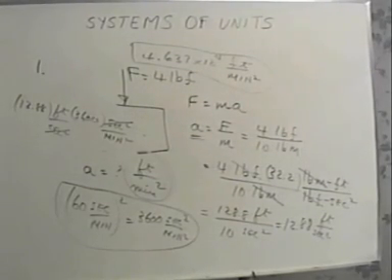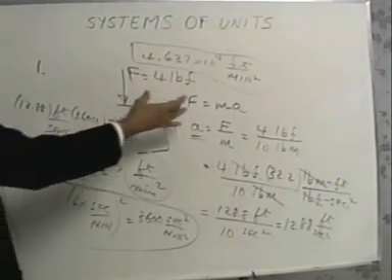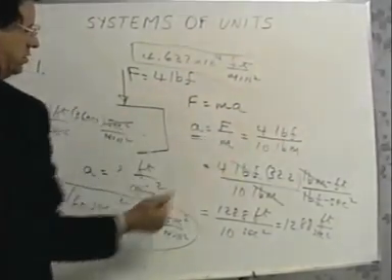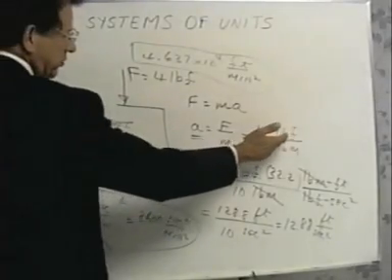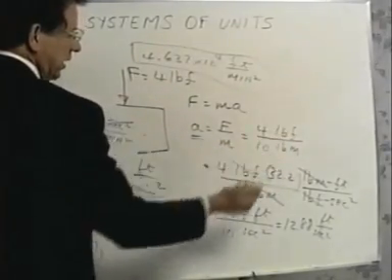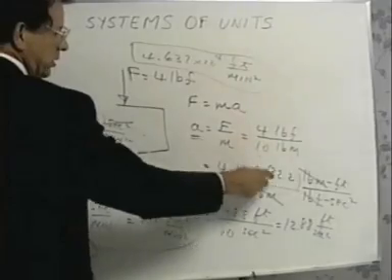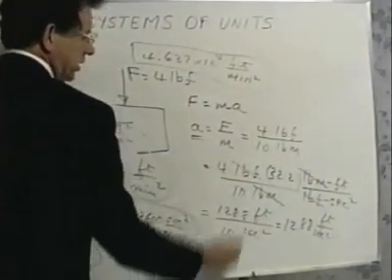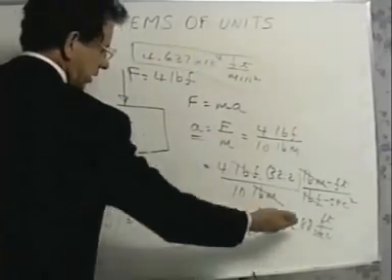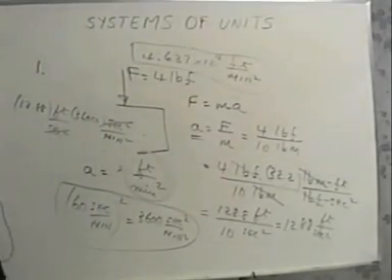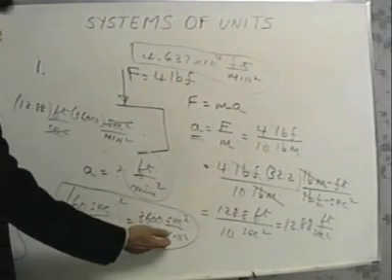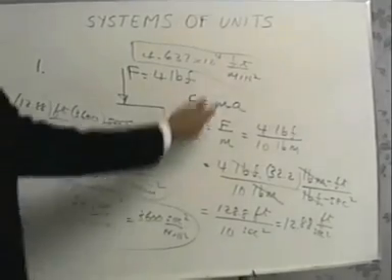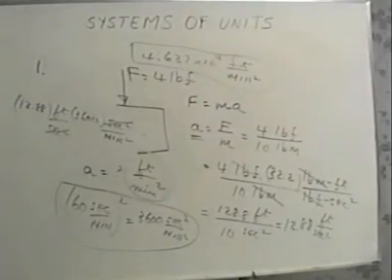So there's the answer. Notice how we approach the problem. We start off by using the basic Newton's law. We watch the units to see how to make things compatible. We know that we need to convert LBF into LBM so we can get a cancellation by multiplying by 32.2 pound mass feet per pound force seconds squared. And that cancels units out very nicely. We get the result. And then as an extra dimension to the problem, we need to pursue in terms of minutes, so we have to make this last conversion. And watch your units carefully. Feet per minute squared would be the final result.